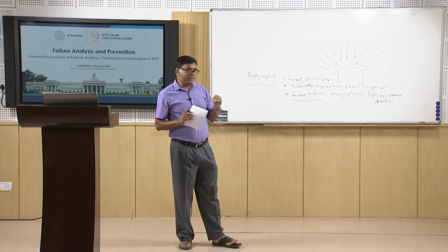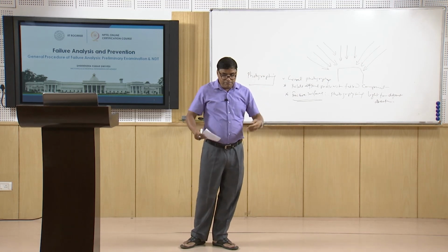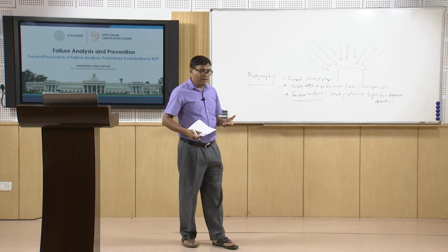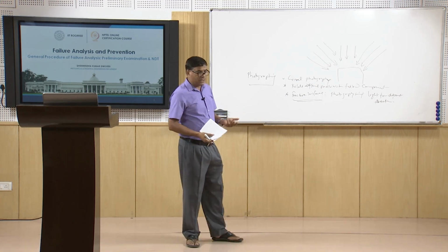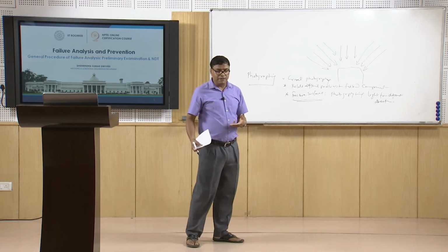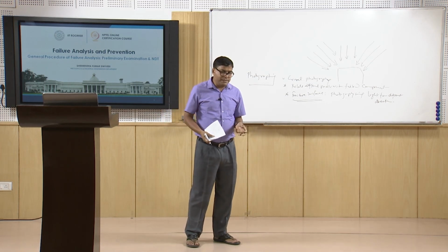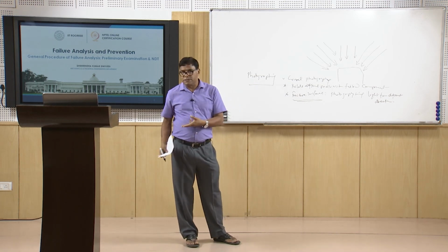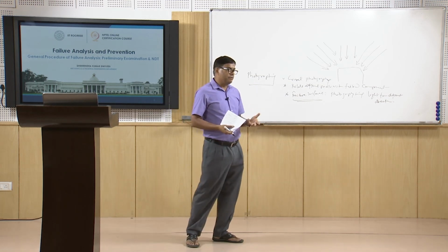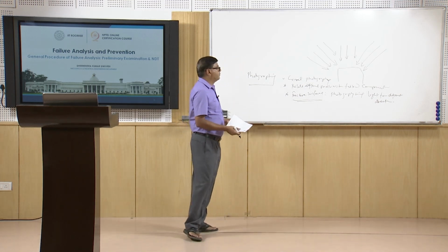So, if the light is directed on the surface in a correct way, then it will be able to reveal or expose the features that are of interest, and that can help in relating with the possible source from where failure has been initiated, the direction in which it has grown, or the possibility for the presence of discontinuity if it is there on the failed components.